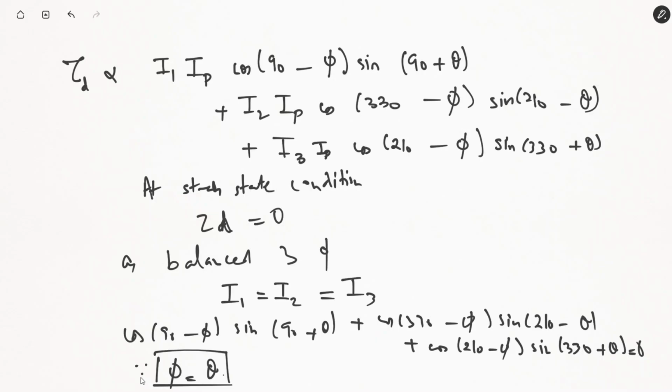So whatever the deflection of the vanes from the reference axis, that will be the measure of the phase angle between the line currents and their corresponding phase voltage. The phase difference between I1 and V1, that's phi, can be measured from the deflection of the iron vanes. That iron vane is connected to a pointer, and that deflection will show us the readings.